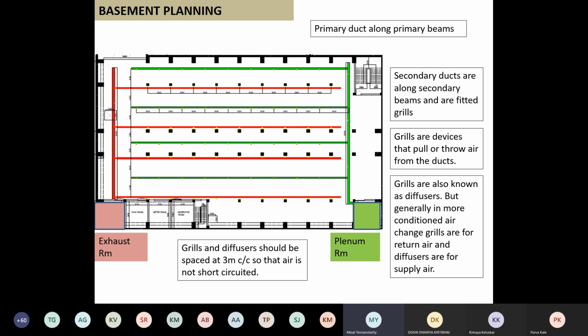The only requirement for the basement is having heavy duty services there, which I can manage with a small one. In such a scenario, people will not go and do this massive kind of double mechanical ventilation. They will only go for one kind of system. Say, I will provide exhaust there. Now, what happens when I provide an exhaust? The moment I provide exhaust, the entire area goes into a negative zone, right? So from the windows, from the ramp, wind automatically starts coming in and aeration happens. And of course, you have fans and everything. So it takes place. But remember, this is only if it is small and there is no parking.